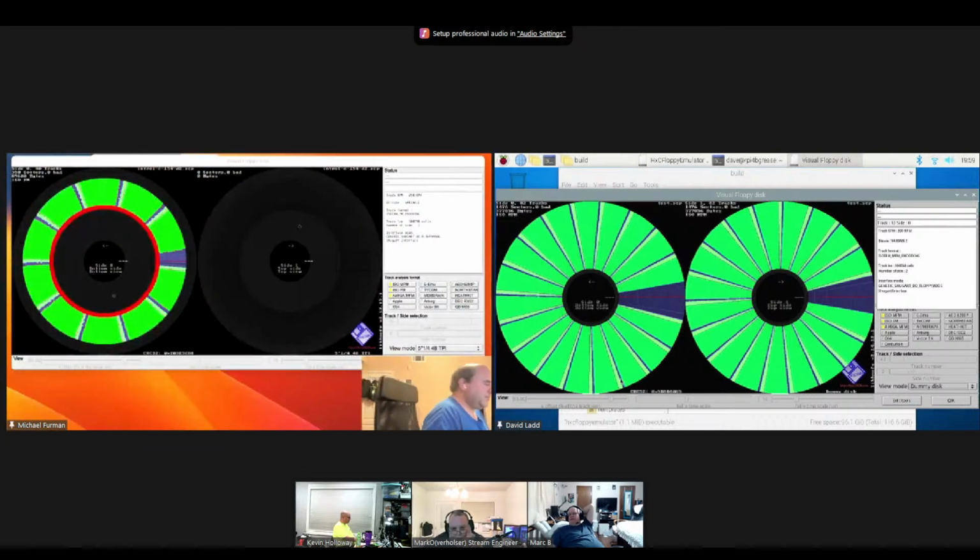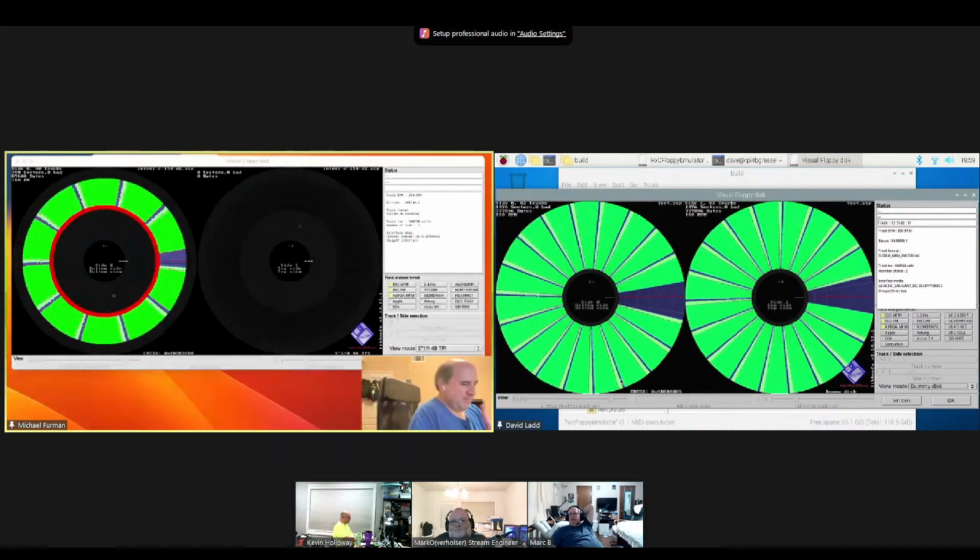Okay, I just didn't notice the first disk you did having a gap like that. Let me finish the explanation. I haven't quite gotten there yet. When the controller sees the index pulse, it starts writing the data. And meanwhile, the disk keeps going around and around. The reason you see this gap here is because the controller wrote all of the data for the track, all 10 sectors, and it had no more data. There's no data written here because these are the ends of the track.